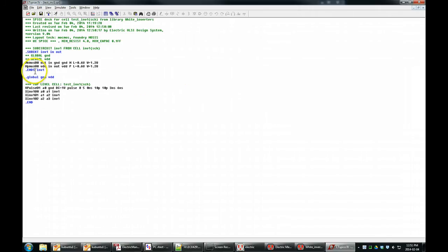If you remember, LTspice complained about not finding a model named N. Here's our NMOS transistor. M, NMOS 0, that's the name of it. Out, in, GND, GND. Four terminals. Here's the model name right there. It was just called N. Well, LTspice doesn't know what an N is. It knows about MOSFETs, but we named a model. We don't have a model definition.